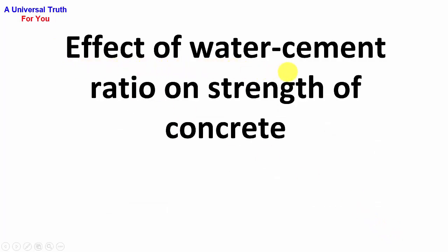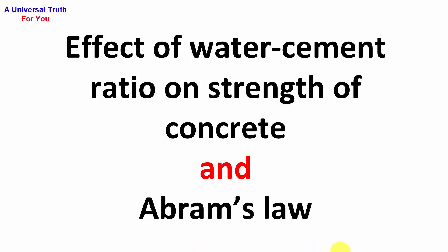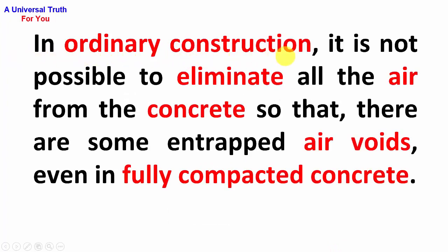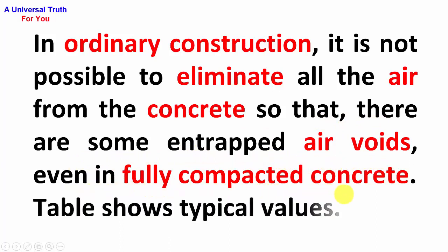Effect of water cement ratio on strength of concrete. So this point will be covered, and Abrams law. This point will also be covered. In ordinary construction, it is not possible to eliminate all the air from the concrete, so that there are some entrapped air voids even in fully compacted concrete.